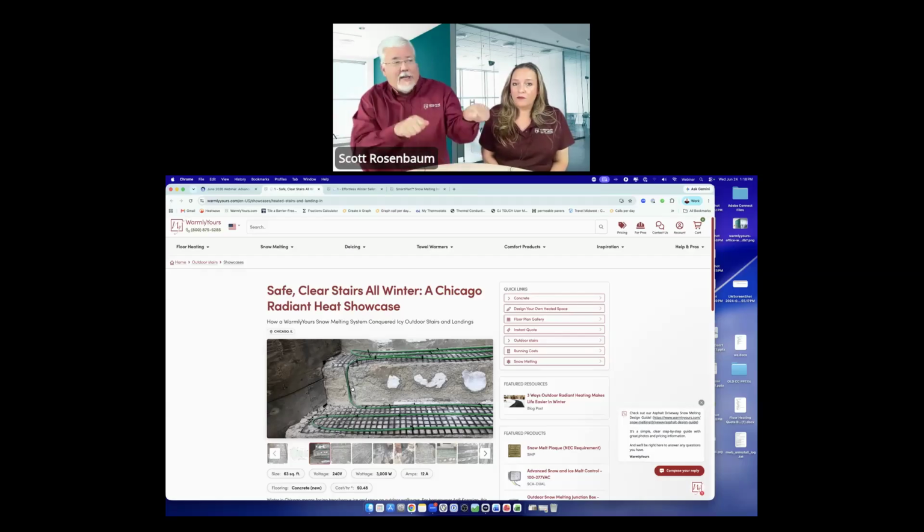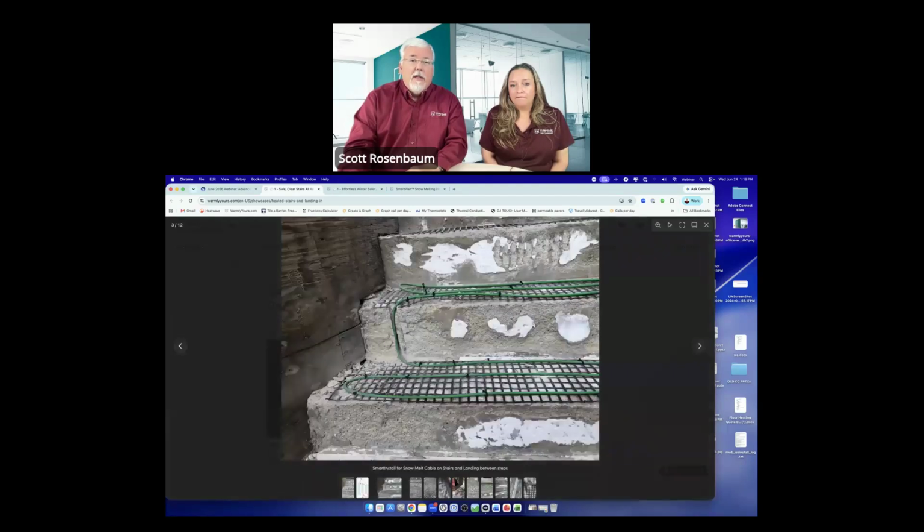Well, as they're moving it like this to get it to set, it is cutting through the cable. Right. So that's why you have to get these recessed. Many times you can do a cut and do a loop like this, and then have it go across the front of the riser down to the next step. In most cases, that's the way it's done. Not a direct 90 degrees, because it can get a little tough on the cable. You can do a loop, do it across the front of the riser, and then go down to the next one. Awesome. That's a great visual.